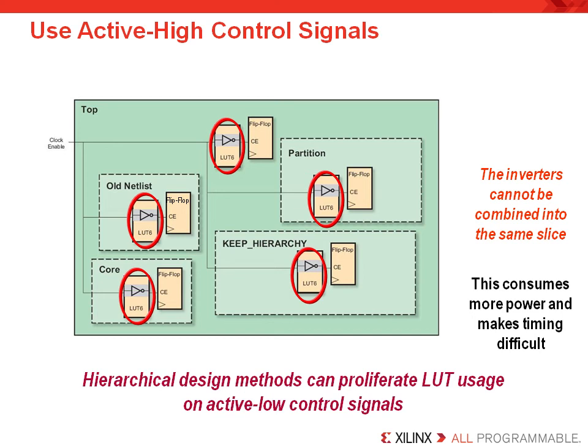Now keep in mind, if these control signals are high fan-out, this might be prohibitive in terms of the number of LUTs you're wasting. So always bear in mind, evaluate your control signals early in the design process, as early as possible.